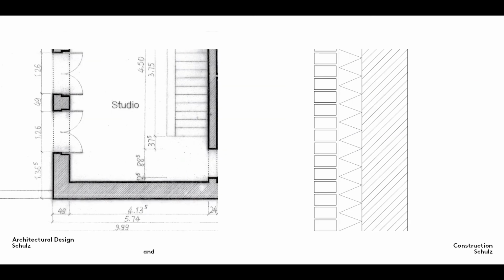For the sake of simplicity, the insulating layer plus finger gap might measure 13.5 cm. The combined thickness of all the layers would therefore be 49 cm, exactly the same as a standard single skin wall. 11.5 cm facing skin plus 13.5 cm insulation plus 24 cm load-bearing layer.